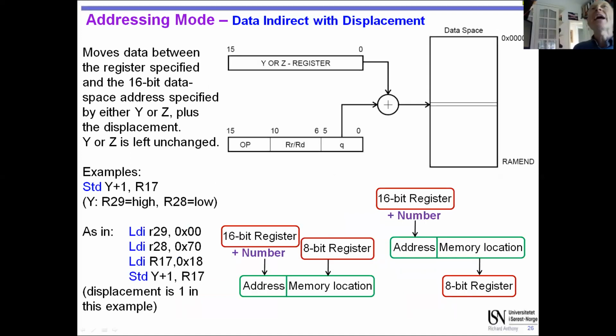And this is the same again, but with adding a fixed constant on, right? Which is this Q value here. Okay. And that's useful in things like copying memory from one place to another, or doing certain sort functions and things like this, where you want to have 2 blocks of memory and you're alternating between the 2 blocks. You're sort of saying, go from this block to the same place in that block, and maybe you've got 2 blocks of memory and you want to add the contents of location 1 and 101, 2 and 102. So this is useful in data processing in loops.